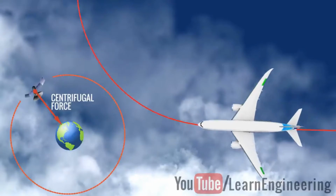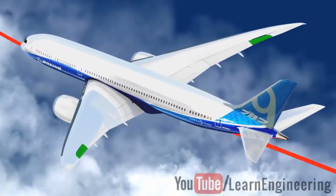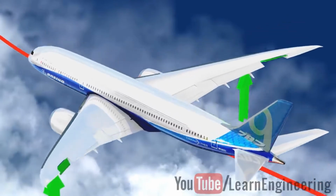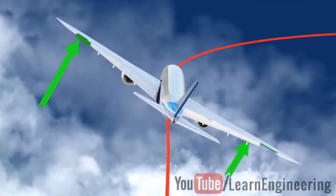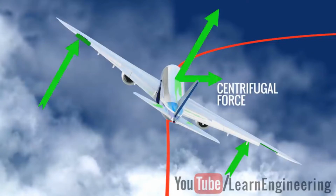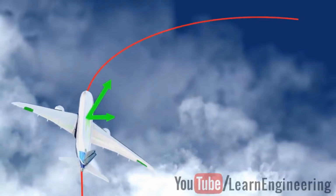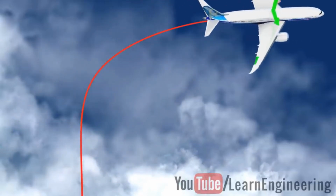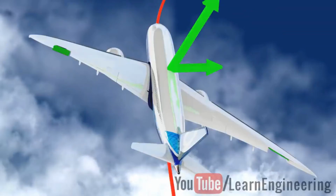Let's see how pilots achieve this centrifugal force. Pilots just make one aileron go up and the other aileron go down. The difference in the lift force will make the airplane roll. In this roll condition, the lift is not vertical. The horizontal component of the lift can provide the necessary centrifugal force to bank the aircraft. This way, the pilot can make a turn of any radius depending upon the angle of roll and the speed of the airplane.